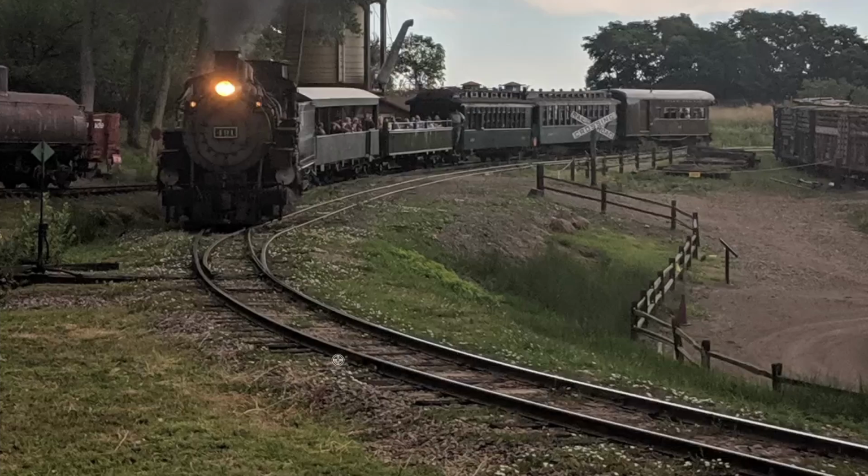Railroad track primarily consists of rails, 2 of them at least, sometimes more, ties that go transverse to the rails or perpendicular to the rails, and then the rails are held to the ties with spikes, and maybe you've seen those in your day-to-day, probably. But equally important as those 3 primary pieces are also the ballast that the track rides on, and then the actual grade that the ballast sits on. So in order to have a railroad, you have to have an actual grade for it to sit on.